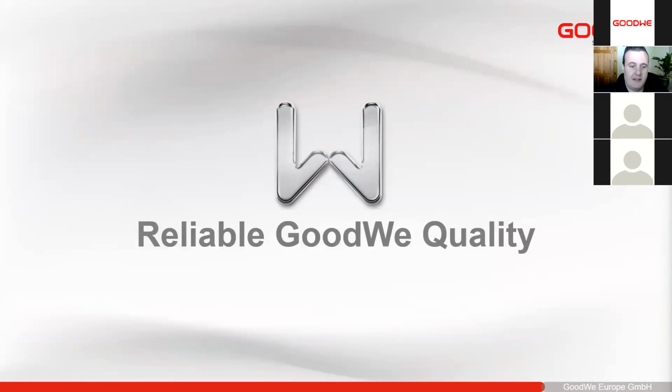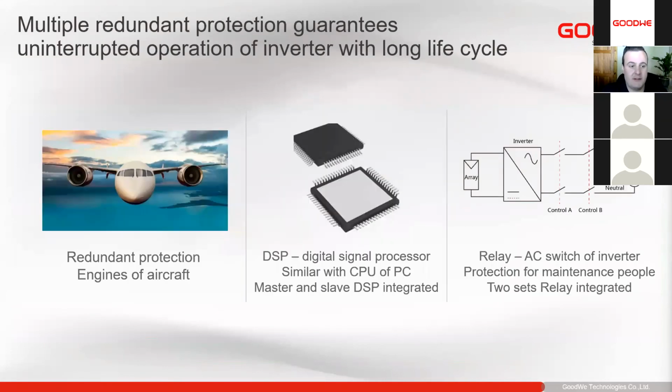Yes, and then just quickly a touch on our inverters and their reliability. All our inverters do have redundant protection internally. We do use DSPs, which are digital signal processors. We have dual DSP processors in there, and all of our relays, especially for AC, we've got double isolation relays for isolation and protection. As is a regulation in many countries, we have this in all of our devices.